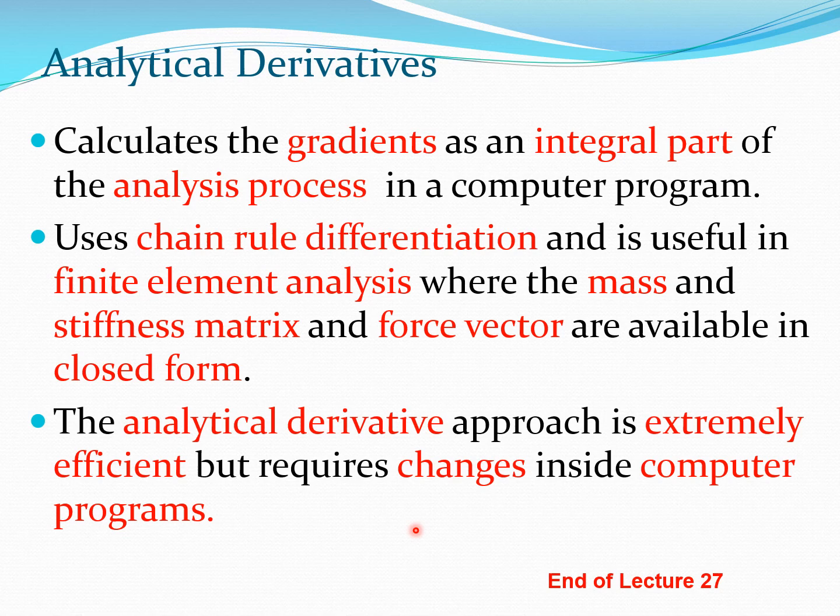For example, once we were doing a problem of stability maximization, and the stability maximization problem was coming at the end of a process which involved solving for frequencies, doing a trim solution for a rotor, and then solving the stability matrix using Floquet theory, which was all very time consuming.